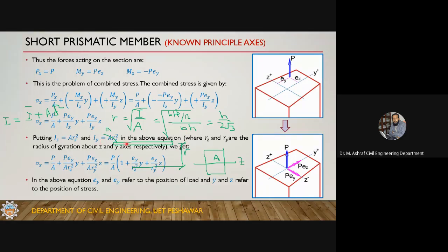So the moment of inertia about its own axis is 0, and there is only A D square, where D is the distance between the centroid of the strip and the desired axis. Since this is r, I will be equal to 0 plus A r square. So I is equal to A r square.